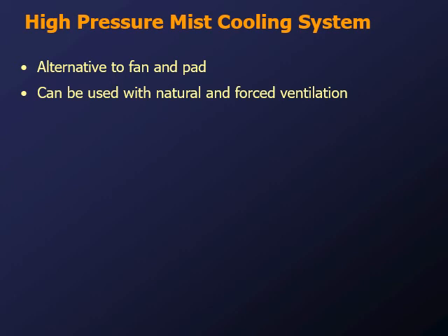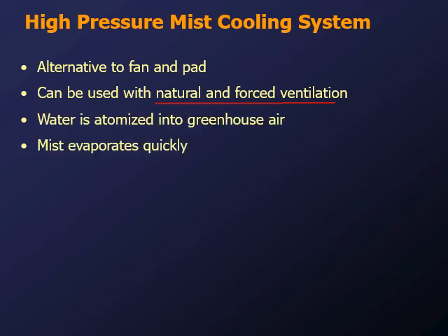If the droplets are too big, they don't have time to evaporate before they fall out of the air and they end up overwatering the crop that's below it. So it has to be very fine mist. Yes, it can be used in combination with natural and forced ventilation. Obviously, you kind of have to make sure you're not wasting your energy on overdoing it.